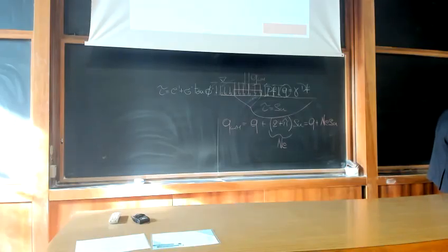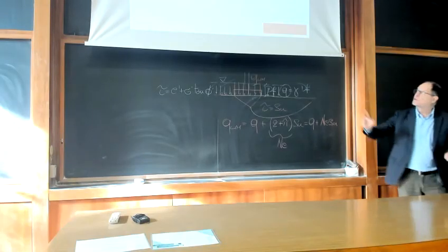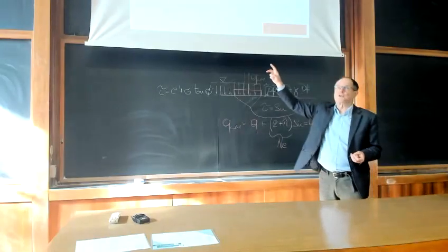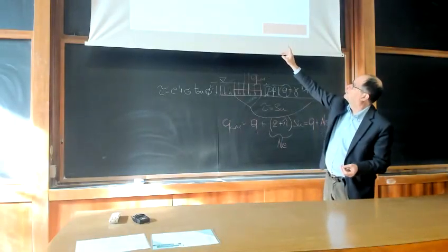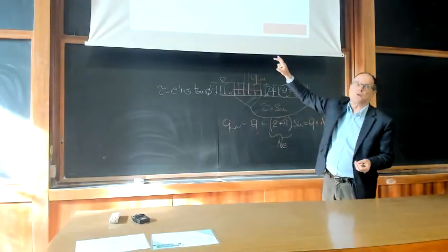But instead of the plasticity theorems, you can apply the limit equilibrium solution, and you can find the equilibrium between a possible Rankine active zone and the Rankine passive zone on the right hand side.